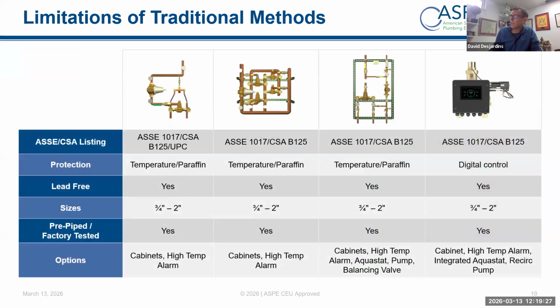Again, so that's what right looks like. When we look at more limited traditional valves, most manufacturers have a standard mixing valve lineup of different sizes, 3/4 up to 2 inch. There's a standard rate of flow. Then they might have another category of valve, with a standard rate of flow but down to lower flows, and that would be a high-low valve. When you start having projects that have flow ranges outside of that, then you put two of them together.